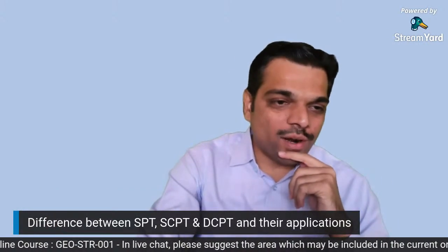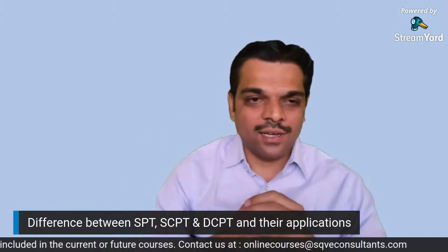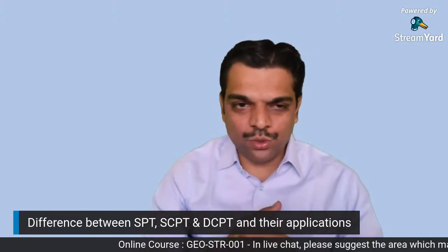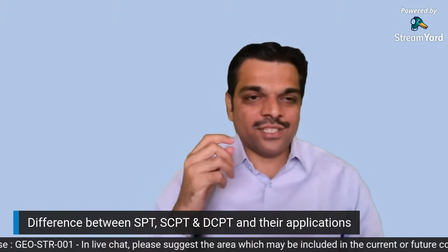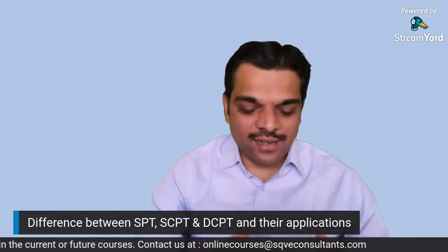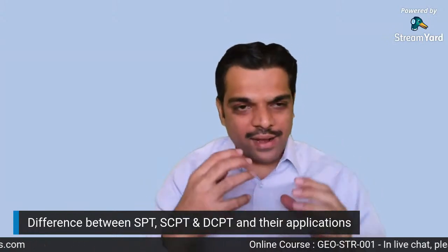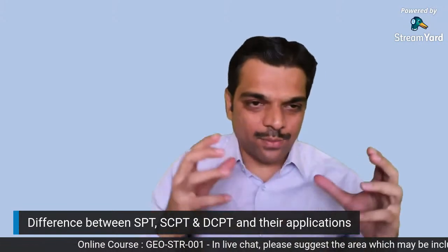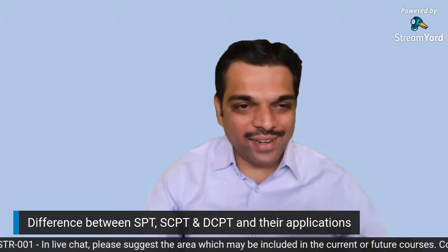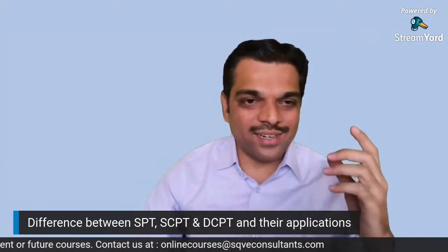Now, this is an interesting question: what are the differences between SPT, SCPT, and DCPT and their applications in different projects? It's a very good question, and we will be covering those details, because it is very important in which kind of project, or rather in which kind of soil, we should go for which kind of test. And of course, let me tell you based on my experience that each test has a kind of uncertainty. As per my understanding, no test is foolproof. There are certain amounts of uncertainty involved. So sometimes we might have to go for a couple of different types of tests, so that we can ascertain whatever we are getting from one test. Secondly, we can compare those details with the second type of test. So it's basically a kind of confirmatory test.